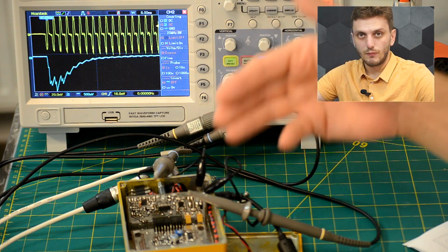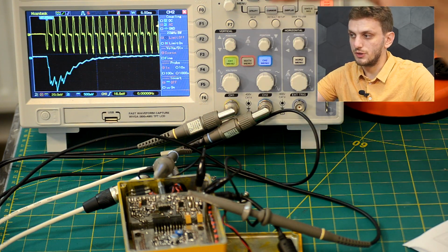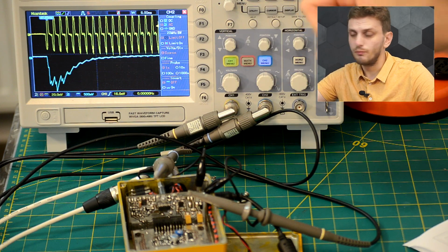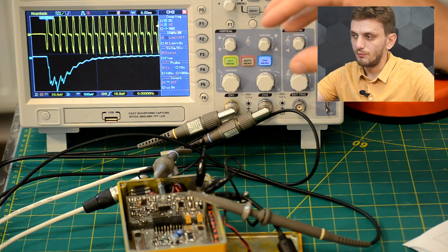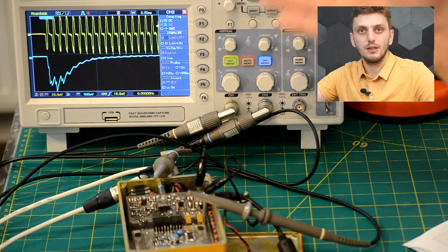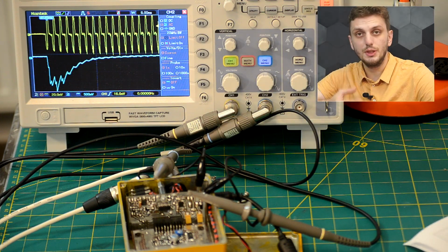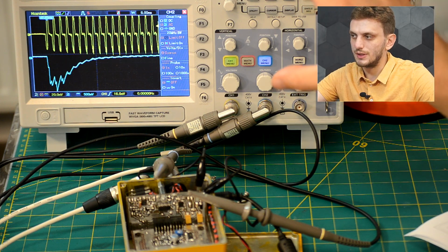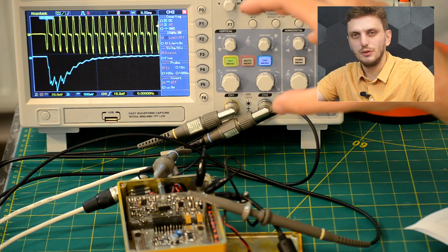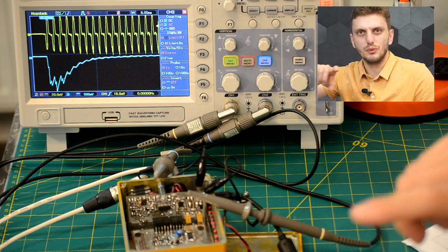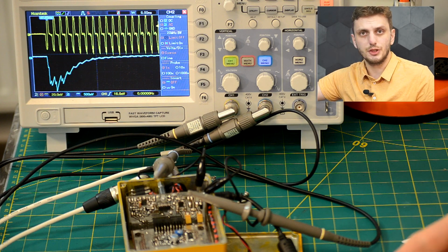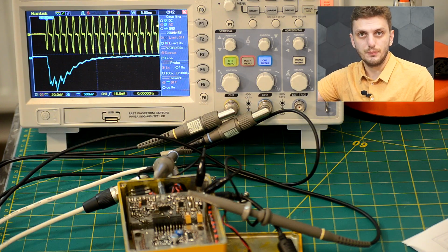Basically, when I had the normal electrolytic, this behavior was far worse. The reason this is a problem is that this voltage gets modulated into the gain of the amplifier. So in the end, the amplifier doesn't just adjust its amplification based on the level of the sound, it also modulates the sound with the sound itself, so you get a very weird sounding effect. By putting in a larger capacitor that has a far lower ESR, this effect is far reduced.